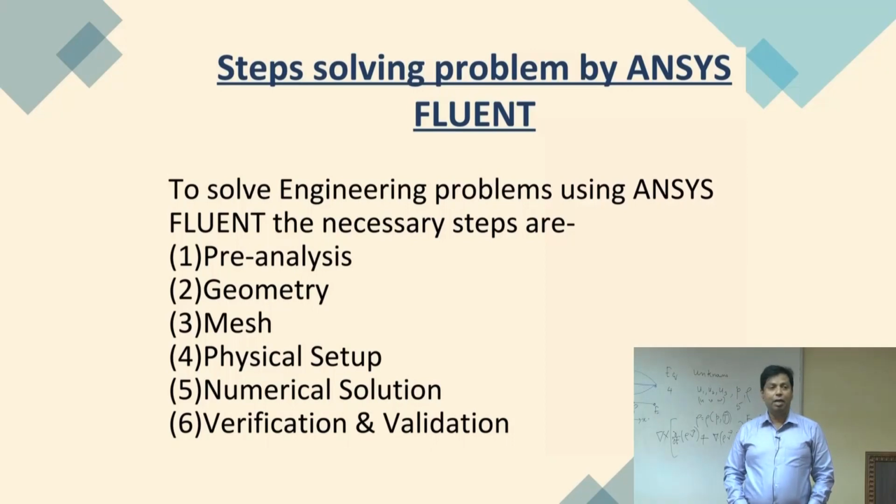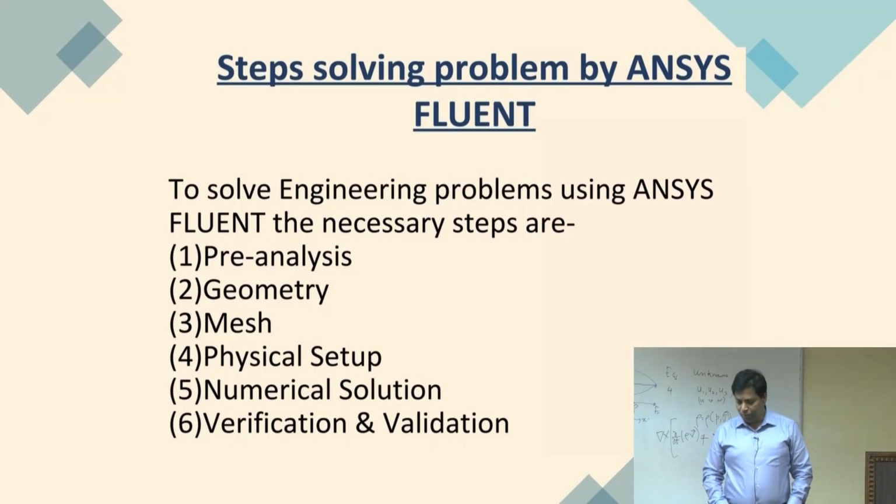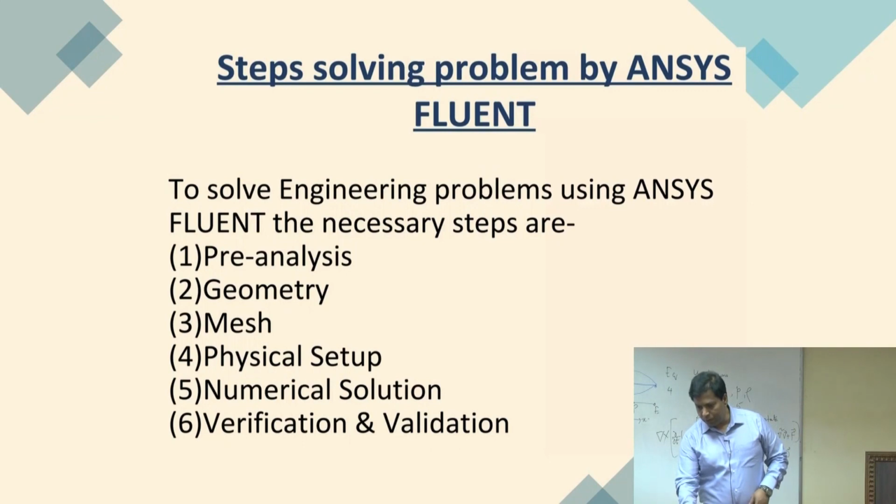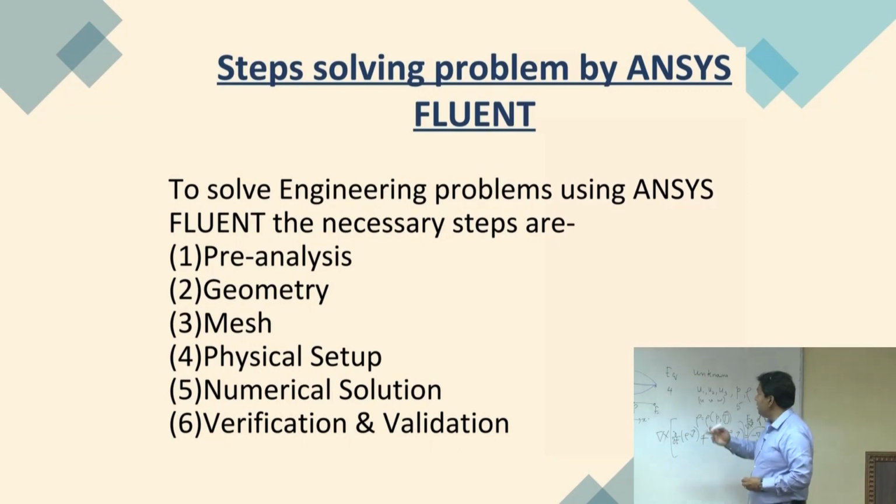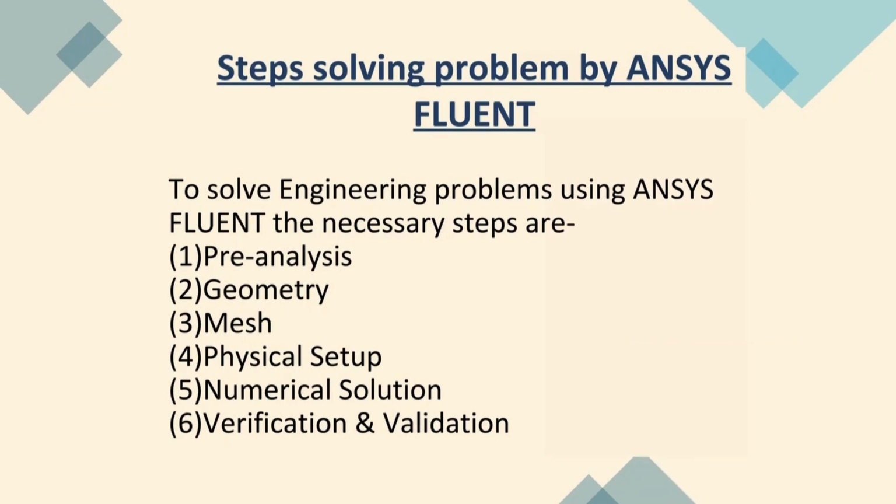You can use any CAD software, but to use it in Ansys Fluent, I think you need to export the geometry into IGES format, .IGES. This format you have to export, and then you can take it directly to Fluent.